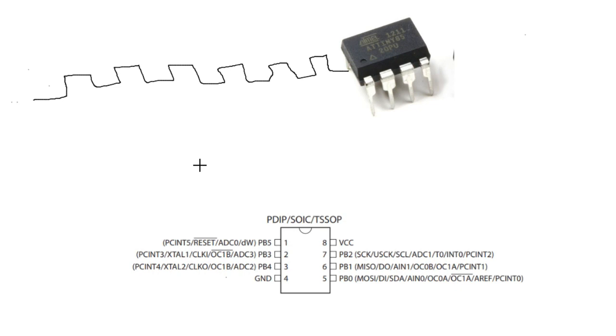Whereas a counter takes its source from the input of sensors, push buttons or any other signal sources. The purpose of counters is to count the number of events or the number of high to low signals, so that we can determine the frequency.